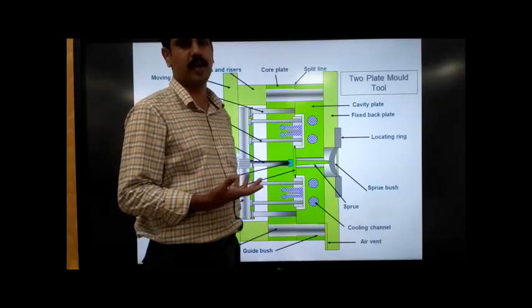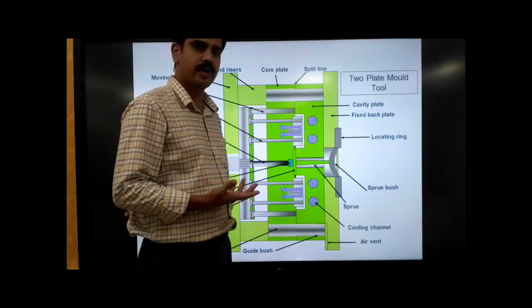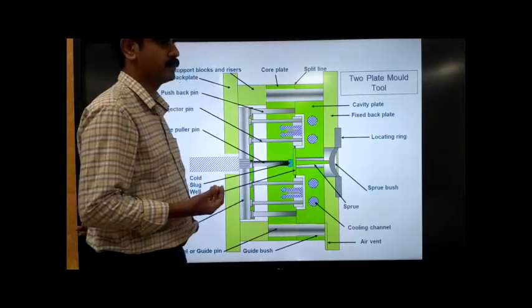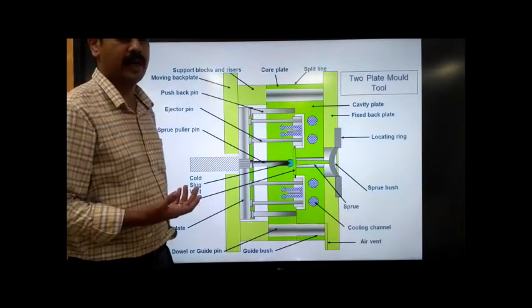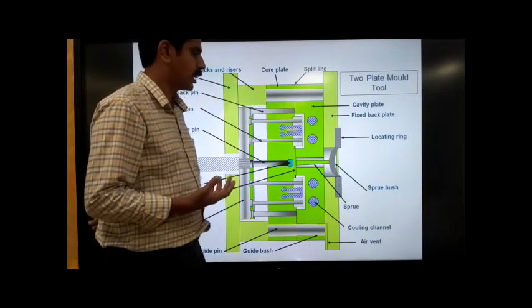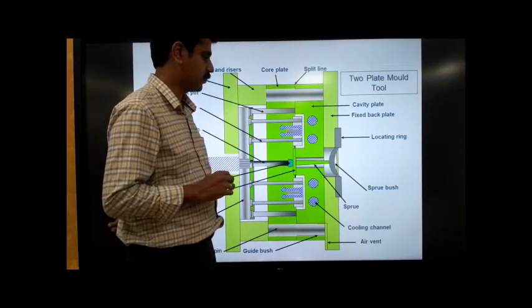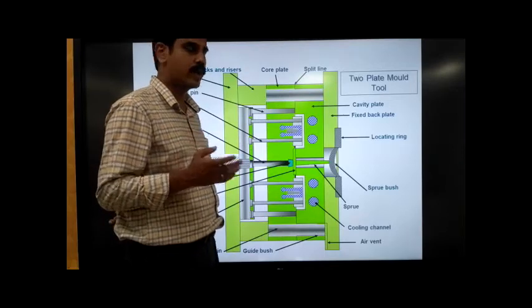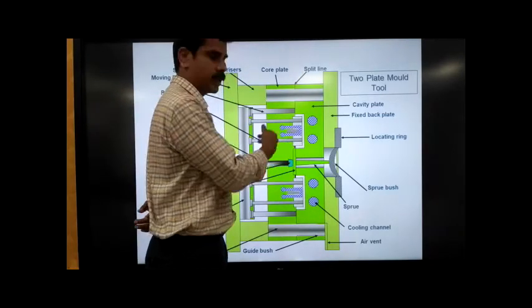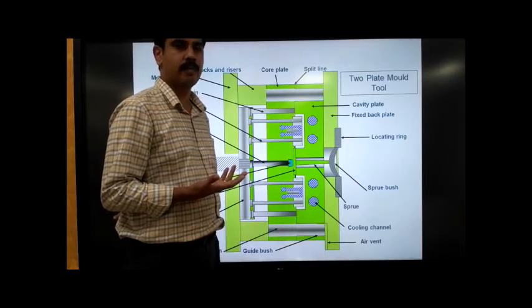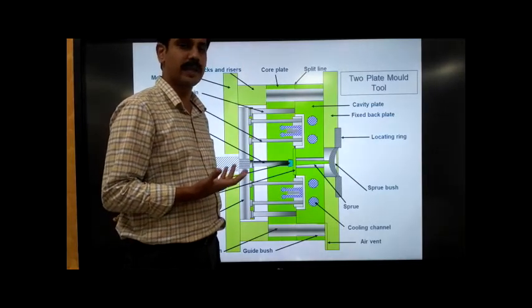When polyethylene is plasticized, we need to take the temperature to a level of 200 degrees if it is high density polyethylene. So this plasticized material is now at 200 degrees Celsius, and it needs to be taken to nearly room temperature. We are looking at a maximum temperature near 50 degrees.